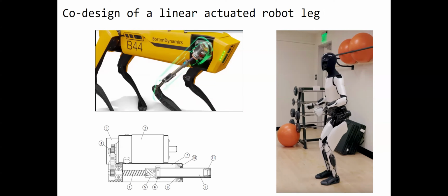But the mechanical system is a bit tricky. Some kinds of mechanical designs cannot move backwardly. They cannot be actuated by external force because, for example, of high friction in gears if you use a reducer, or some kind of tricky geometry of the linkage.